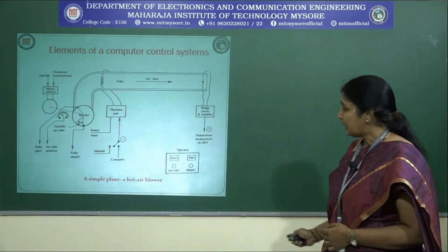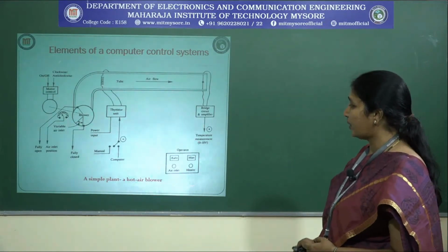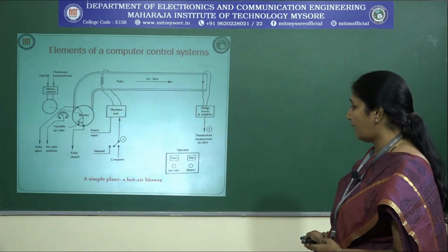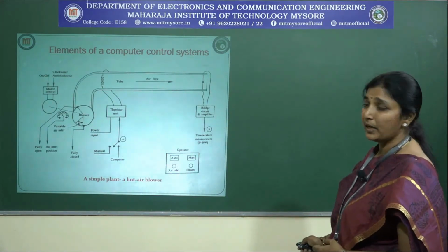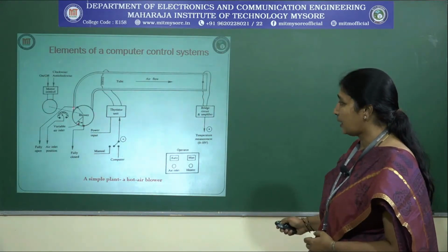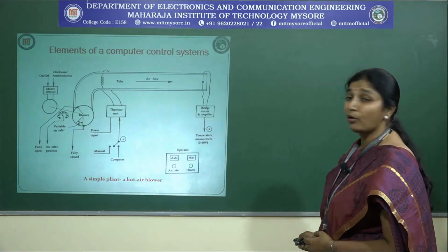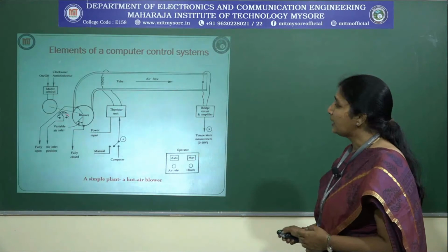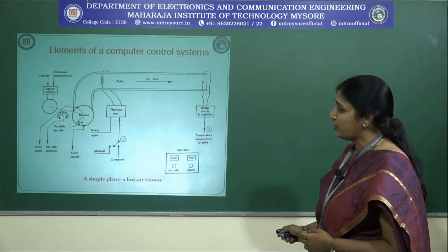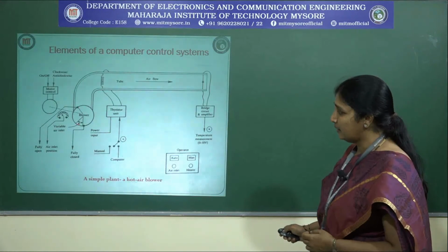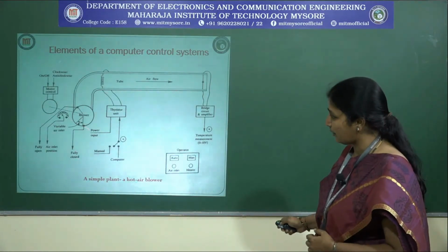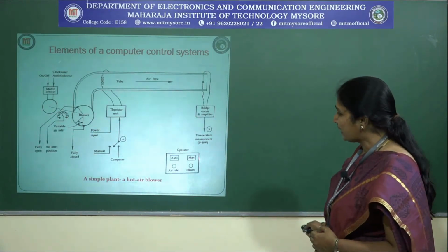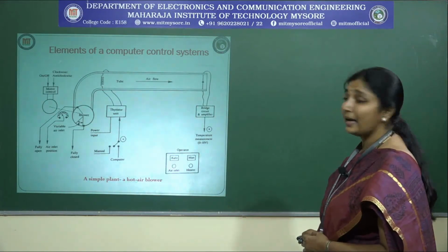By controlling the inlet air, you can control the hot air that will be delivered out at this outlet point. And here you can also see another panel mainly used by the operator. You have auto, manual, heater and air inlet. This cover here completely opens and closes. That can also be manually operated by an operator. He can just press manual and vary the potentiometer here to let air in, completely closed or completely open. He can set the angle for the air to blow. So that can be a manual operation to let the air inlet.